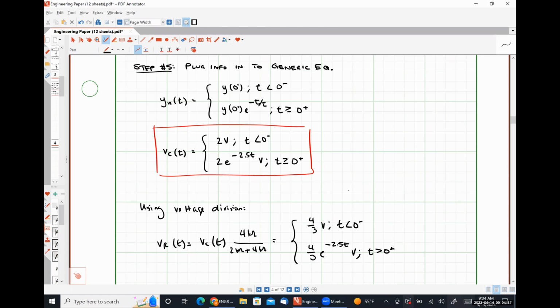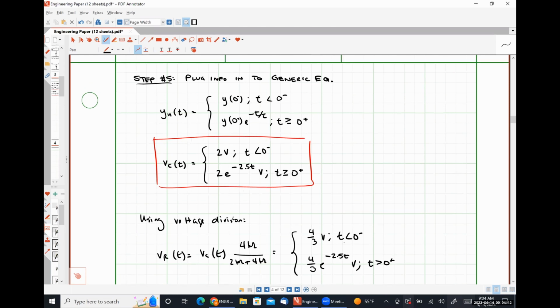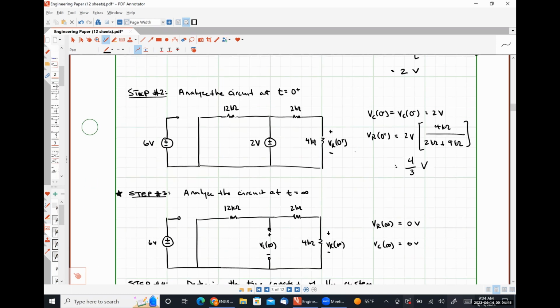So we know that if the voltage drop across that capacitor is of that exponentially decaying form, then the current flowing through the 2 kilohm resistor and the 4 kilohm resistor have to be of that exponentially decaying form because of Ohm's law. And then using Ohm's law again, the voltage drop across either of those will be of that same exponentially decaying form, right? If one thing behaves like the exponential decay, all of it does. It will either be 0 or the exponentially decaying.